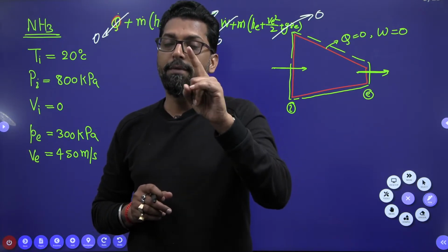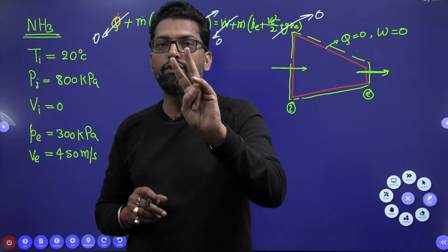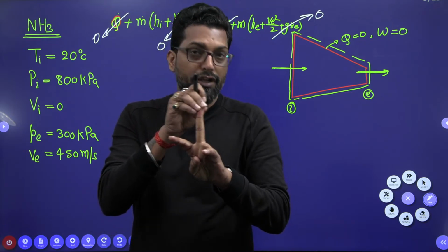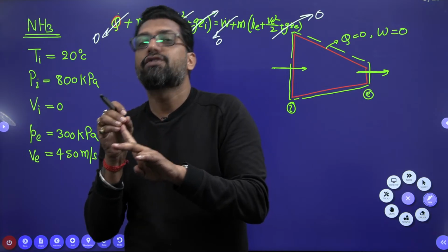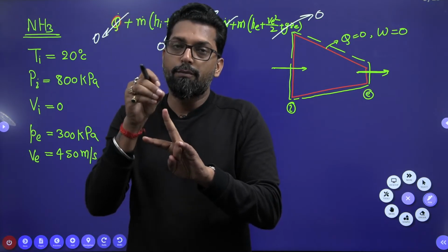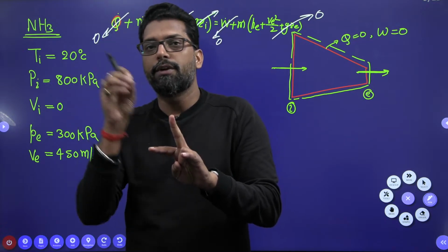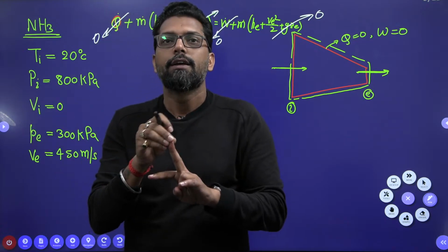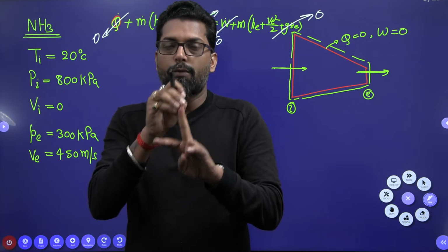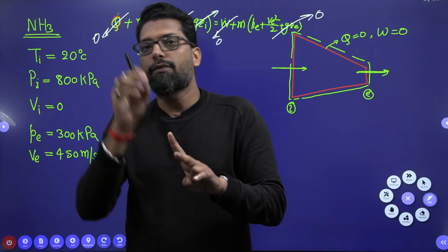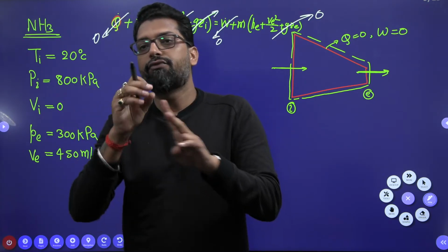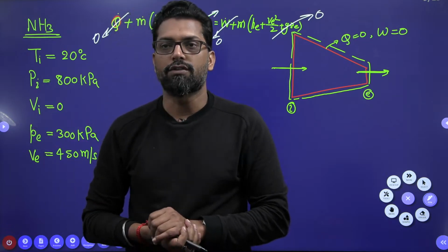Now, conservation of momentum, we apply to two types of fluid. First is the inviscid fluid, and second is the viscous fluid. So if you apply conservation of momentum to an inviscid fluid, the final equation obtained is the Euler equation, and if the fluid is viscous, the final equation is the Navier-Stokes equation.